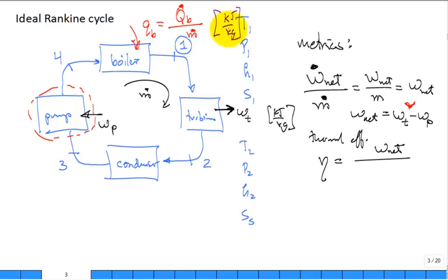It does. Have you analyzed heat exchangers in the previous chapter, boilers? Yes, just like we analyzed pumps in the previous chapters. We're just putting the pump, the boiler, the turbine and the condenser into a cycle. So here we're going to have QC, lowercase qc, going out of the condenser. Notice this is shown to go out. That's a positive heat transfer out of the fluid that's passing through the condenser.